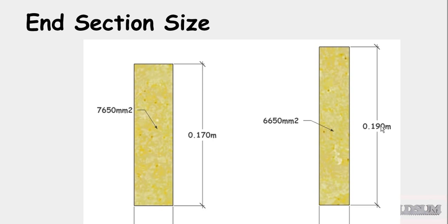However, if you look at a piece of 190 by 35, which is the next standard size up, it only has 6,650 square millimeters. So there's less timber in this beam than there is in this beam, and with all things being right, the less timber, then the less price. So to be more efficient, we should use the 190 by 35.